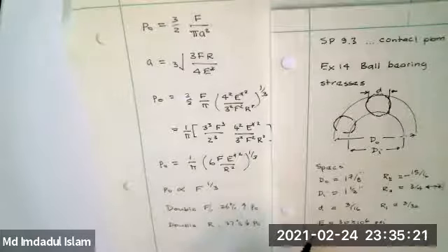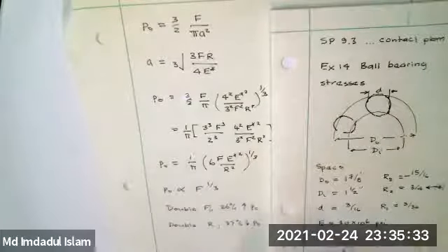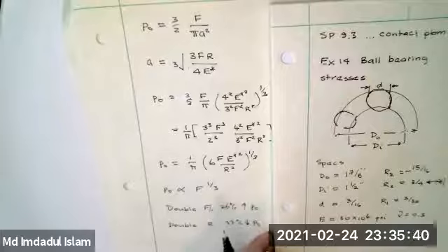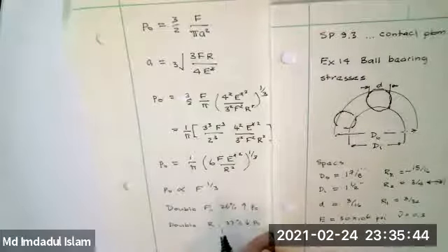If you want to get standard values for any material, you can go to the appendix in the back of your book, and those are accepted values. You would only change them if somebody had done some testing at your workplace and had a specific value. And a common value for the Poisson's ratio taken for steel is 0.3. Again, this varies some too. On the other hand, typically these variations don't make a lot of difference.